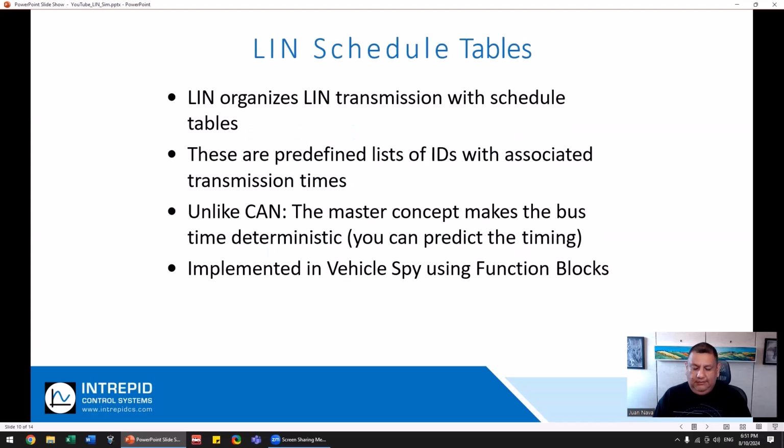Okay, so the thing about schedule tables: there are LDFs that have one schedule table, and there are times where they have more than one. It just depends what the system might need to do. If the system is slow normally and something gets changed, the system can change to the point where these messages become more frequent. So instead of going maybe every 300 milliseconds, for example, they could get down to 100 milliseconds as an example. Diagnostics tend to be in the 10 millisecond range. Generally, I've never seen anybody run faster than that.